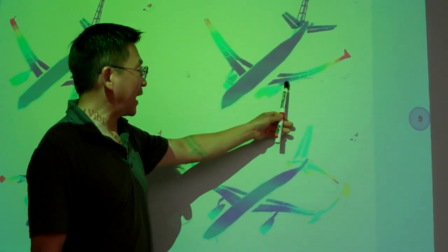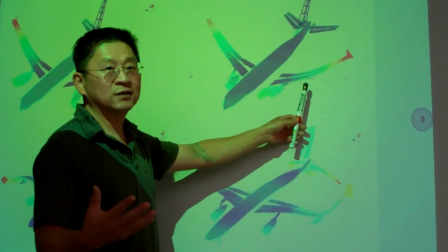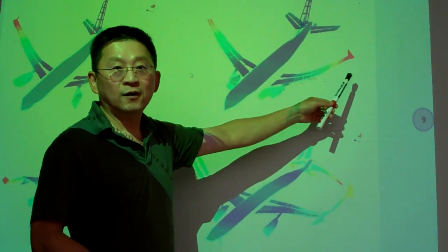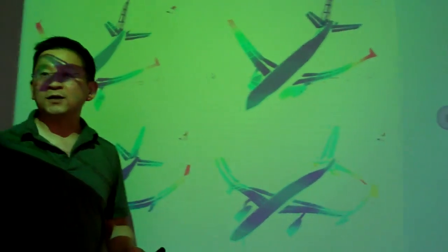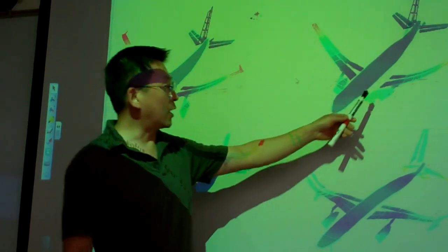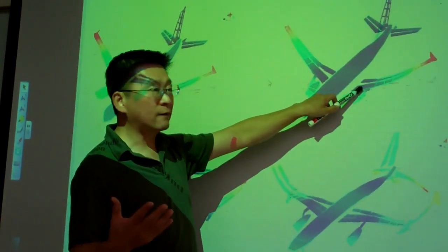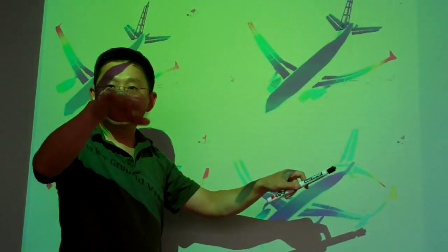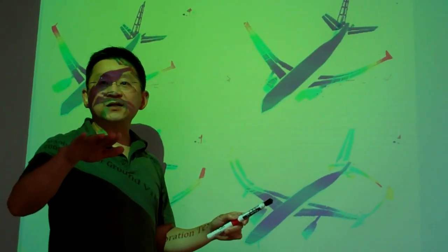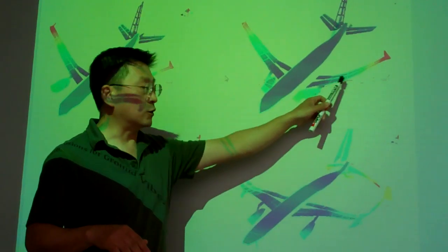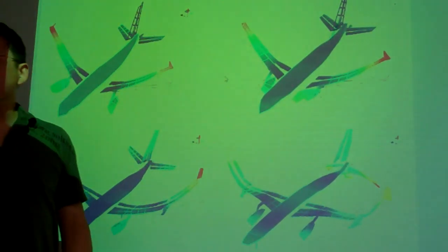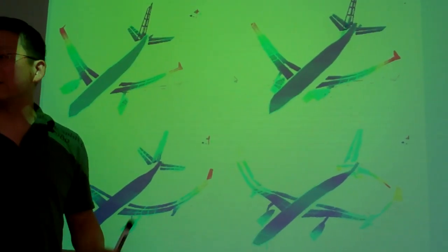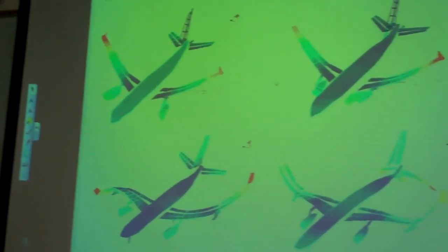They hang different bags of sand, of different mass and weight, at different locations to simulate static loading, and then they use certain motors to drive the wings to vibrate. So they study the vibration of the wings under different loadings, and that's the way they do physical testing to extract some information. So that is one example here.